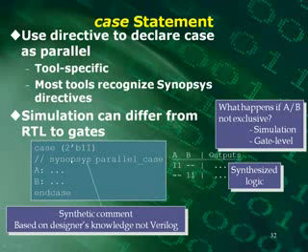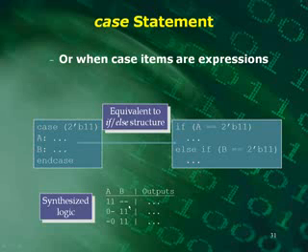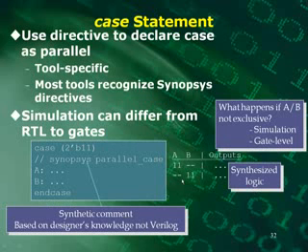So in this case, if this were the Synopsys compiler or one that was compatible with it, then if A is equal to 2'b11, the output would be whatever this is. And then for B, it wouldn't be that if-else. It would just be: if B is equal to 1,1, then you get the output. It doesn't care what A is. Whereas in the previous example here, it does matter. Anyway, I just want you to be aware of this.